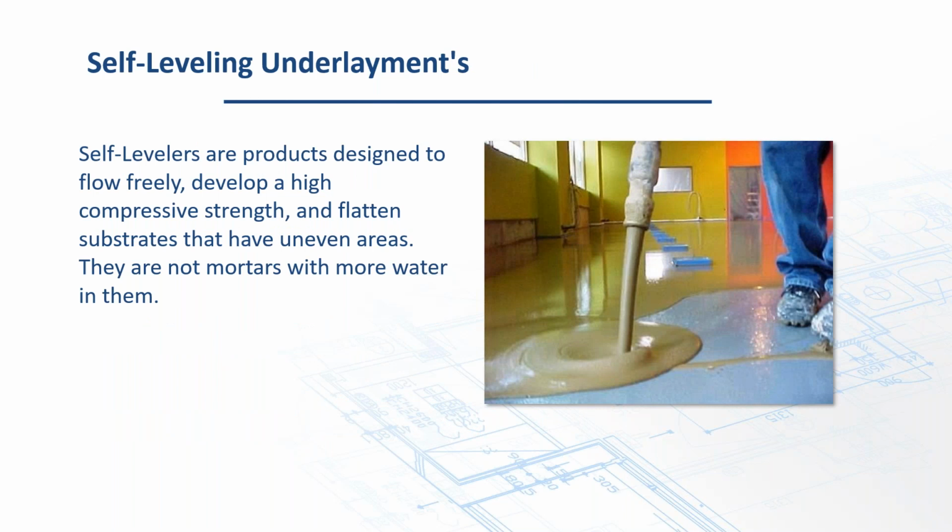Let's talk briefly about self-levelers. As I said, the other flooring industries have been using them forever. Resilient floor covering inside, self-levelers were critical to them, been around forever. They've been around in the tile industry, but really not as common. They're getting more common today. As a matter of fact, quite often they're replacing mortar beds where a mortar bed would have been more appropriate.